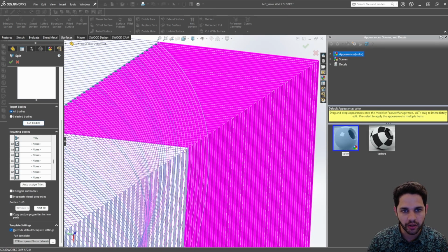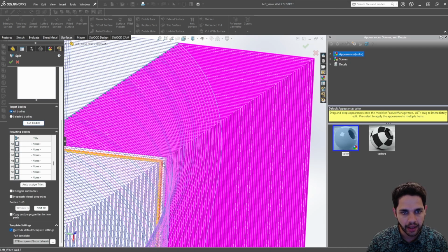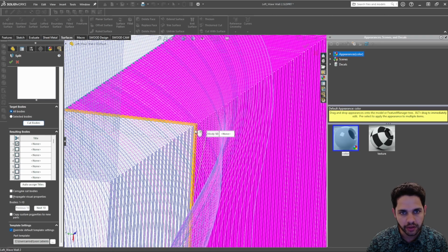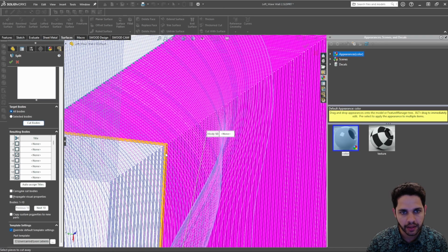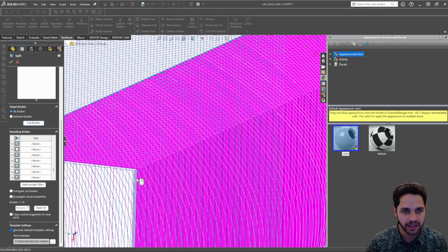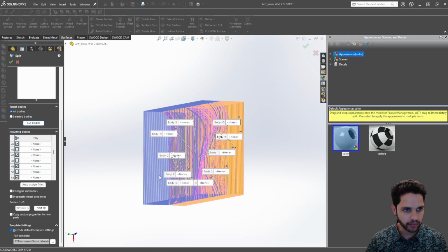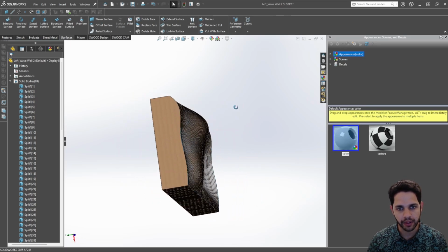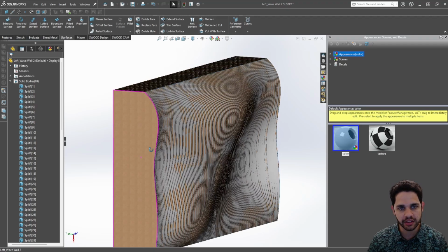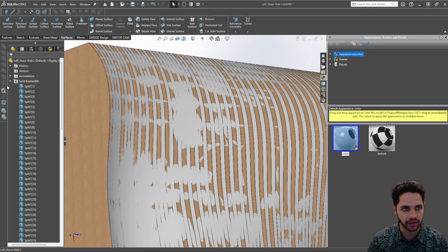Basically what we want to do, we want to select all these panels, and we're going to consume these panels with the cut. And I'll show you guys how to do that. So boom, boom, boom. All of these are going away. Hopefully my computer can handle this computation. Awesome. All right, so all those are selected. So what we're going to do, we're going to select this consume cut bodies, and we're going to accept that process. And when we do that, we're left with just the side that we wanted to keep, and our geometric surface body is still here as well.